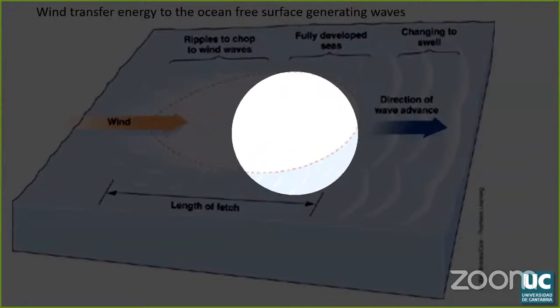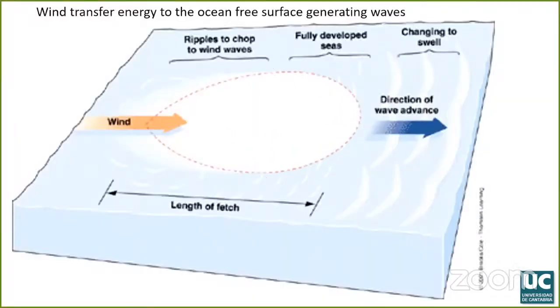At the beginning of a storm, waves have little energy, a short period and a low height. As the storm continues, the waves transfer energy from the short periods to larger wave periods. The longer the duration of the storm and the larger the fetch, the greater the wave height and the wave period, until it reaches a state of equilibrium.